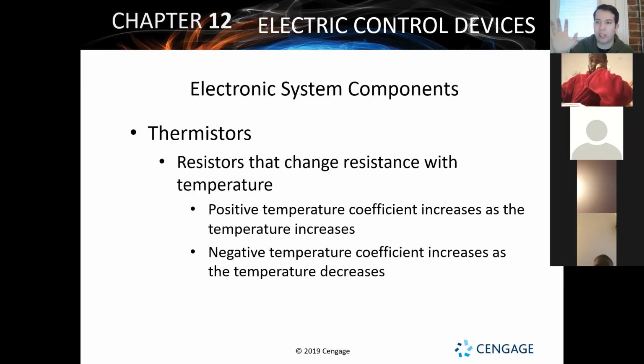So let's say we have the main thermostat sitting in the downstairs hallway on the first floor of a 2-story house. All right, on that first floor, it's reading 73. We're doing fine, nice and toasty, no problems here. But upstairs, we can put thermistors in each of the rooms, and they can feed information back to the main thermostat telling it yes or no if it's gotten to that temperature. And as it gets to the temperature that the thermostat's set at, it will open and close dampers inside of the ductwork to either allow airflow to go to those rooms or to stop airflow. Oh, it's gotten to temperature, stop the airflow. We don't need to go in it.